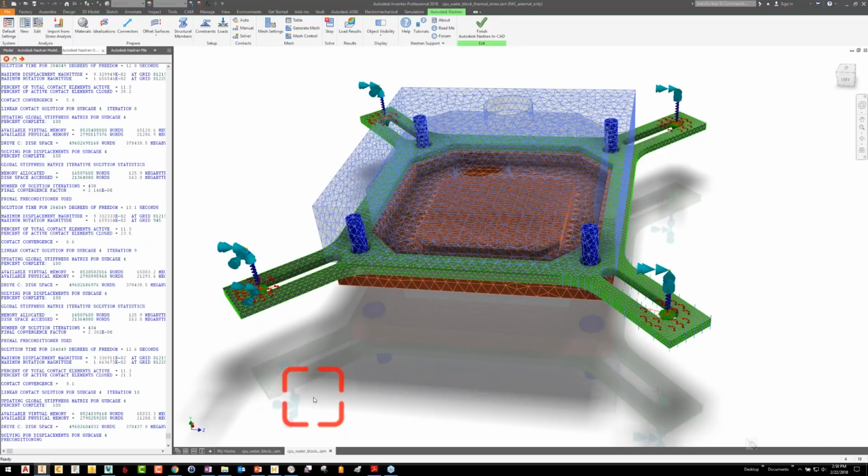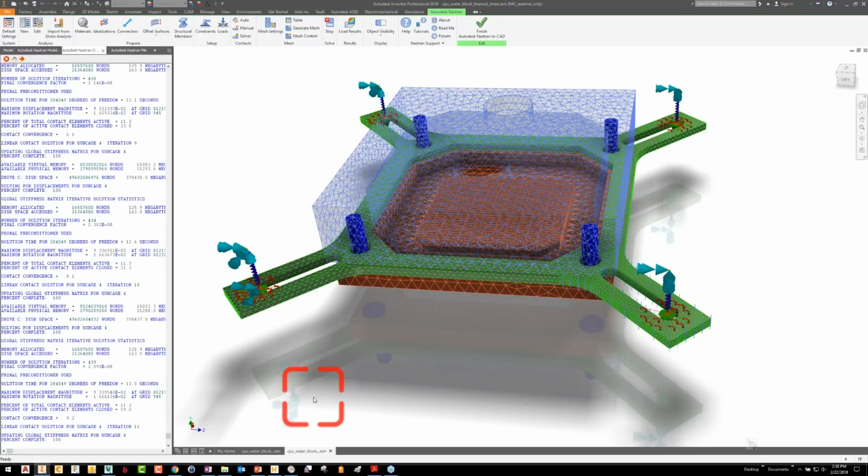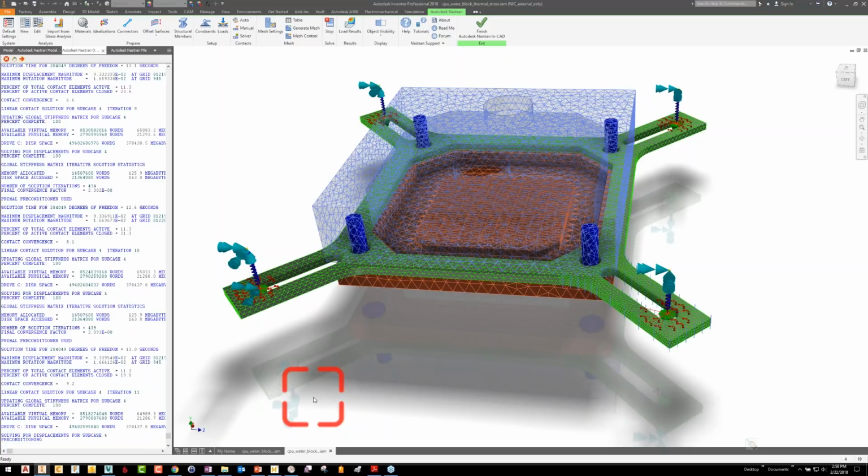And then it'll do it a third time and check to see how much it's changed from the second to the third run. And it'll keep doing that until it's detected that it's not changing so much anymore, and then it figures, hey, I must have come up with the final balance between contact area and forces. So it's not something that can be solved in one shot. It has to iterate. So you'll see in the log iteration 11, right?